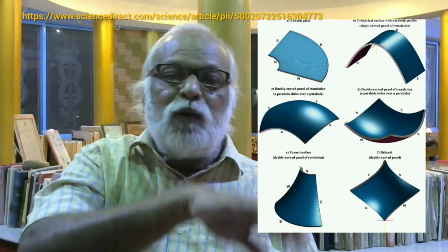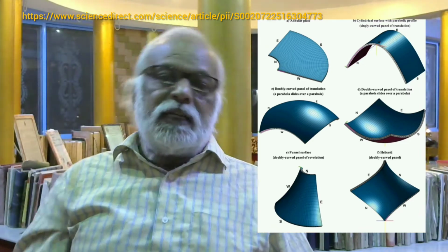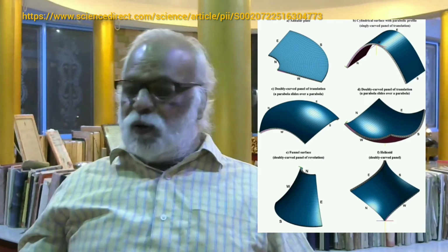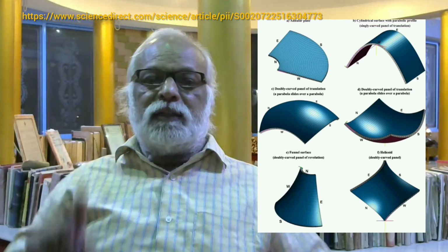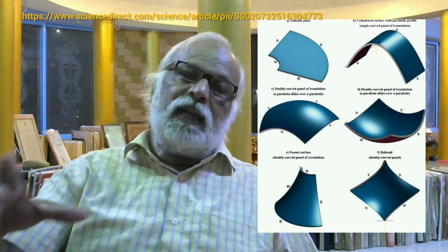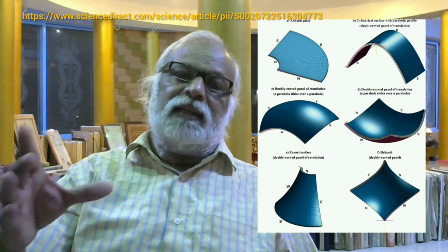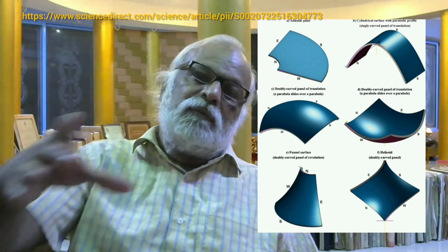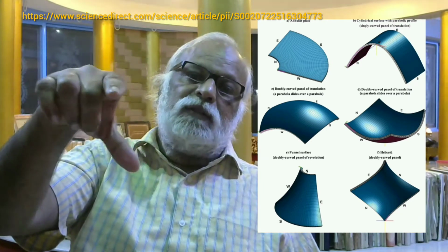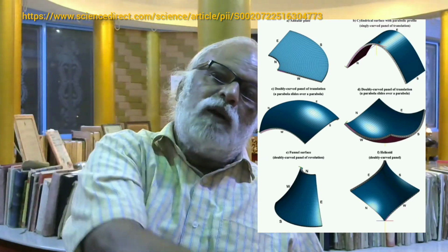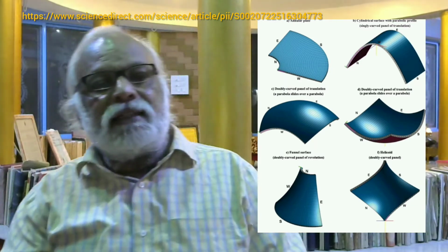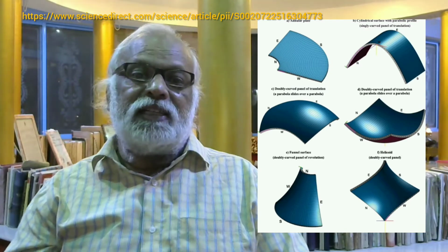Cylindrical shell. How will you get a cylindrical shell? Just have a circular arch, a semicircular arch. Then go on, one semicircle after the other. Just go on sliding a linear element, a line from the bottom apex, that center point is called the crown of the arch, the crown of the shell. Go on sliding it down. It is a shell of translation. A cylindrical arch is a shell of translation.